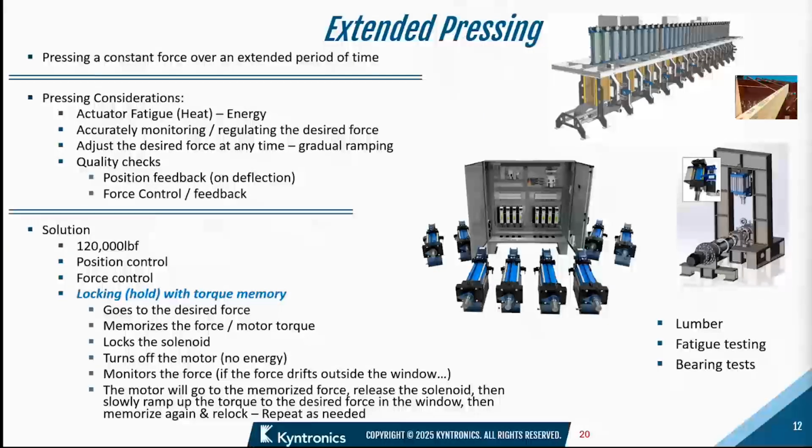So our solution was a 60,000 pound force solution. Position control, force control. So if they went down the road of hydraulics, it had to be 33 cylinders, a big, huge hydraulic solution that's pumping all day long, taking a lot of energy for those 30 minutes and pressing that 60 tons each actuator, and having the flexible control is a challenge.